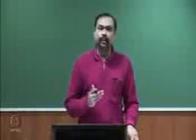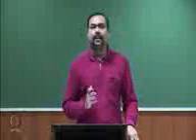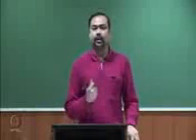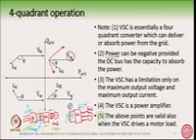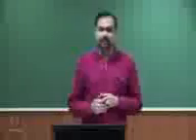But you understand that power can be negative from the VSC provided that the DC bus has the capacity to absorb the power. This capacity is present in the battery. The battery can absorb the active power, but a capacitor does not. A capacitor also has it, but for a transient duration, not for a long duration.